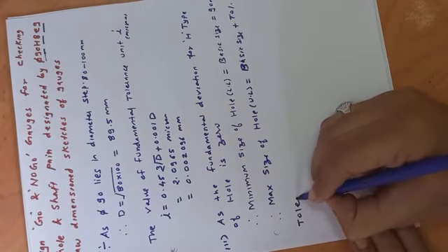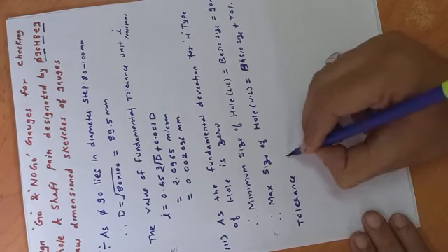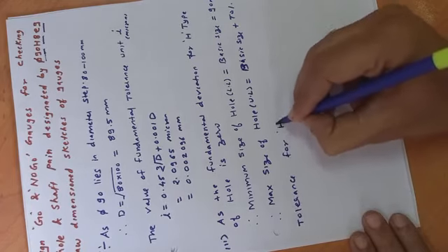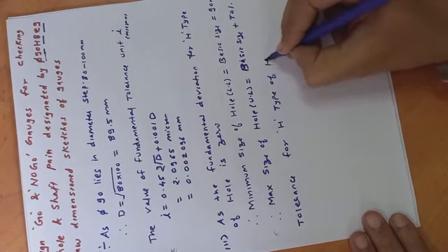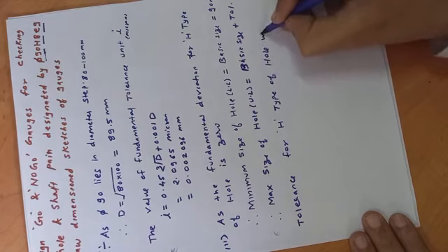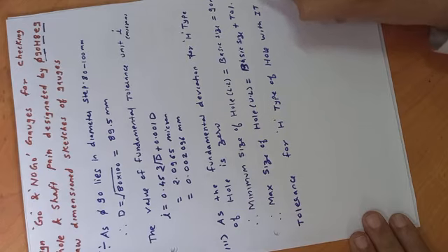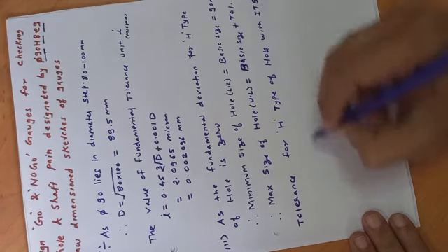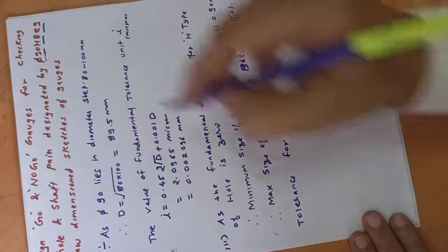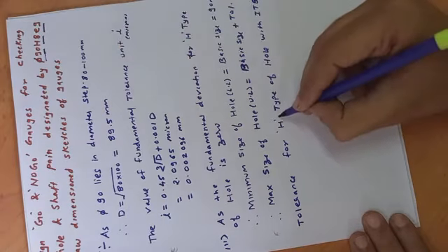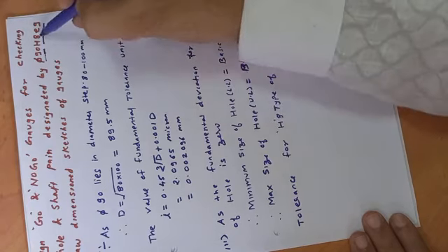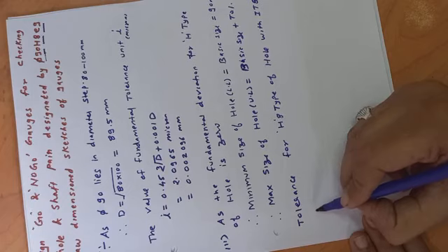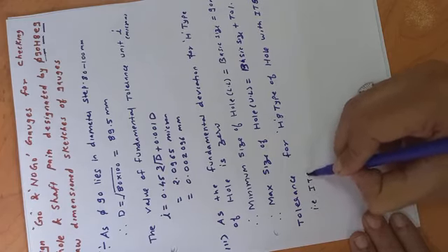So the tolerance for H type of hole with IT grade 8. Here it is an H8 type of hole, so having this IT grade, that is IT8.